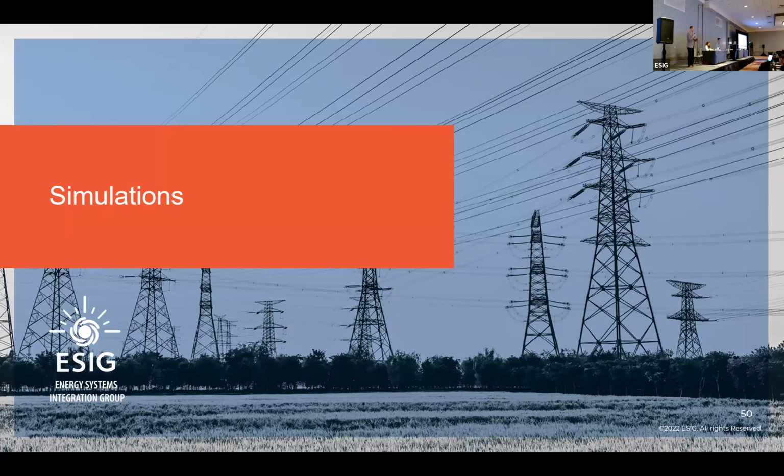That said, what is common is that if it impacts the performance in a material way at the AC, at the grid connection side, then you need to have that in there. For instance, if you do have a technology where you have trip thresholds based on DC quantities, you need to have enough representation there to capture that. I'll start there, or maybe pause there.